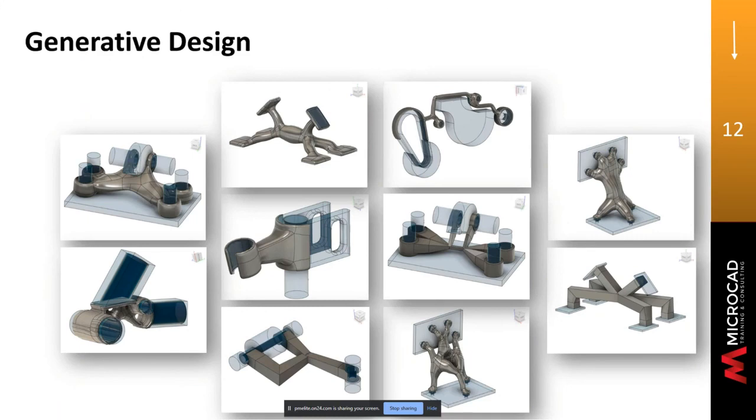And I would note, from personal experience, that the generative design configuration process is similar to your analysis process. You go in, you set constraints, you tell the computer what surfaces you're going to use, and you set your loads and everything, and it will take over after that point. It will give you several iterations of your design, and then you can select which one looks like it will work best for you. Once your generative design is complete, you can actually go in and manipulate the model further.